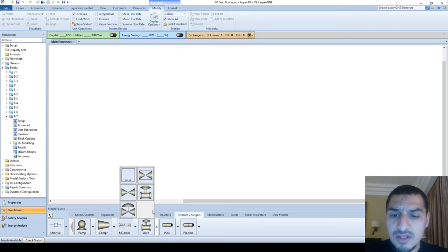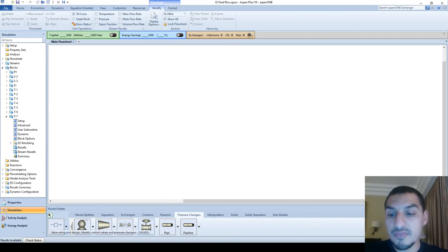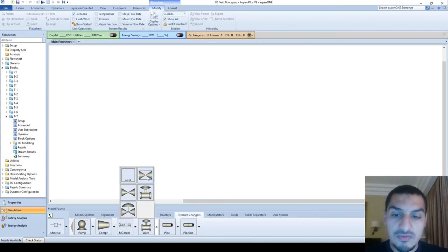The third is the valve, and you'll find that there are many shapes of the valve, and the valve is, as we all know, used to do some control on the flow. We have a valve rating and valve design, and we know the difference. The rating is that we put the specs of the valve, and we want to see how the output will look like. And for design, I want to get this output, and I want to find what design of the valve I need.